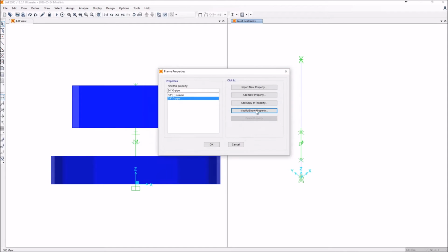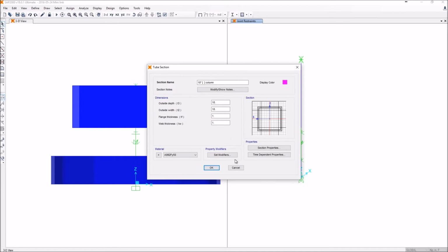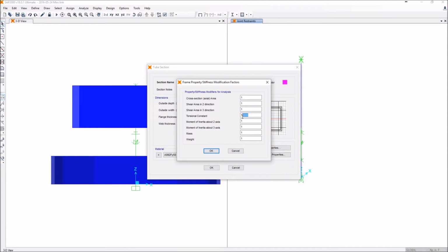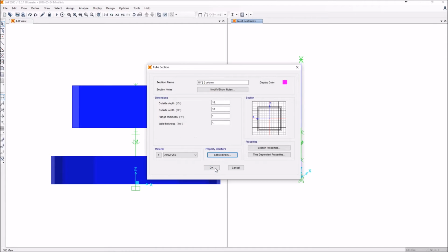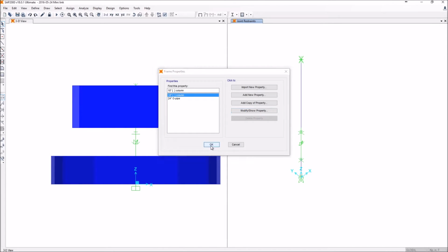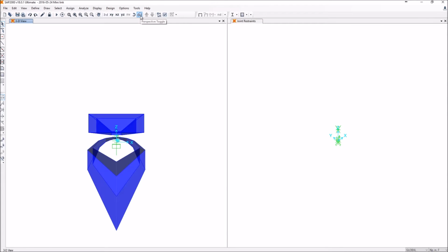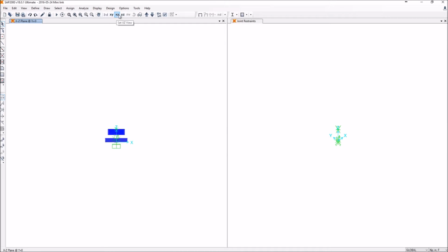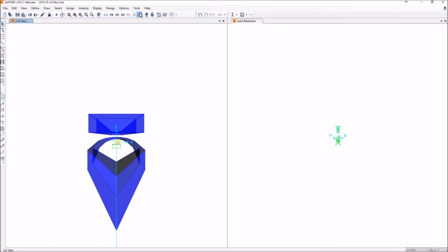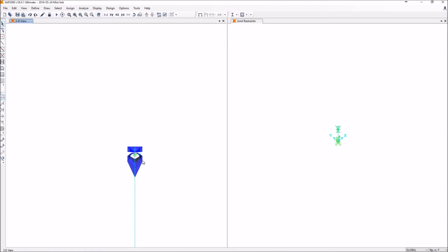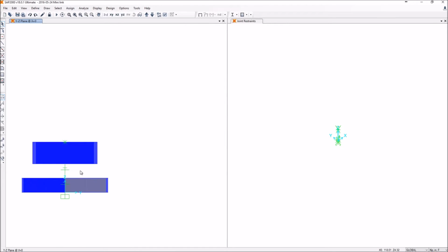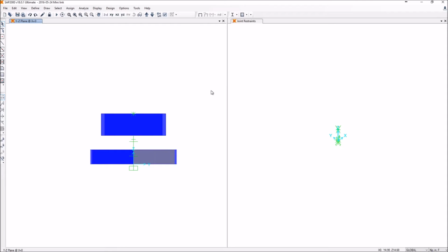And here we see the properties in the stiffness file. As I was playing around with the model, I modified the torsional constant, and now I set it back to 1. Now I'm going to show you how the model looks. Basically it's a small, 6-inch-tall profile. I didn't want deflections to come into play, and whatever deflections we did see, I wanted to make sure the solution time was small. Whatever is visible here is actually similar to the model that I have in ANSYS.